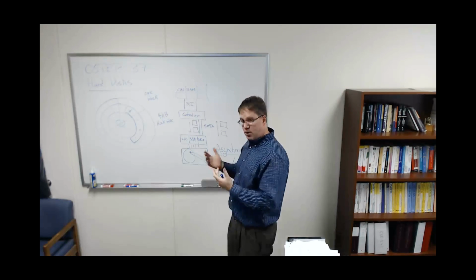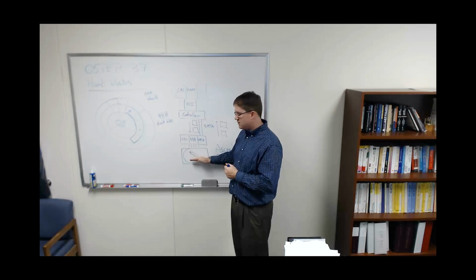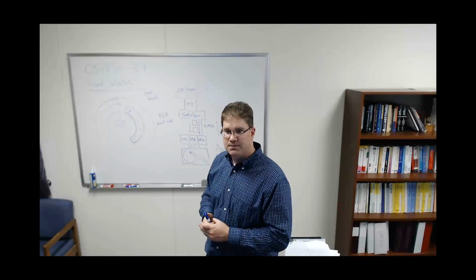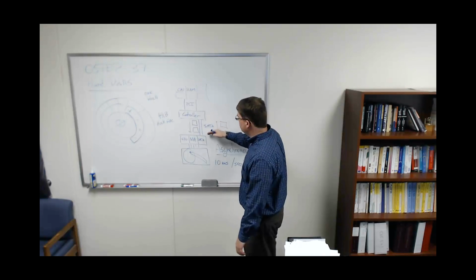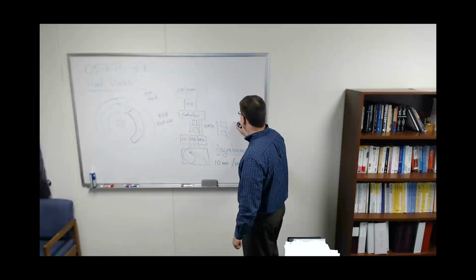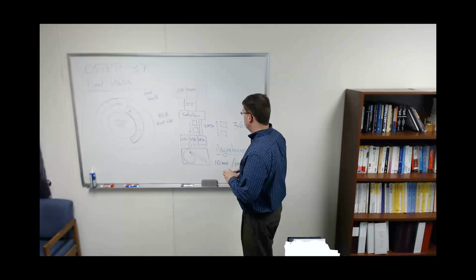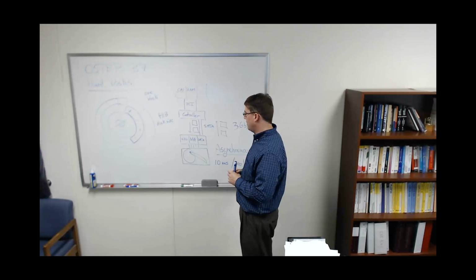And the simplest approach we can do is to say, let's try to put things in an order so as to minimize the amount of distance that this arm has to travel. If we can do more work with less arm movement, then we'll be able to get a higher throughput out of the disk. Now, how high can we go? Well, I'll tell you the limits. If we're using a SATA interface here, the electrical limits of the SATA interface are about 3 gigabits per second. That is a lot of data. That's the fastest we can move this over these wires, just as defined by the electrical limits.